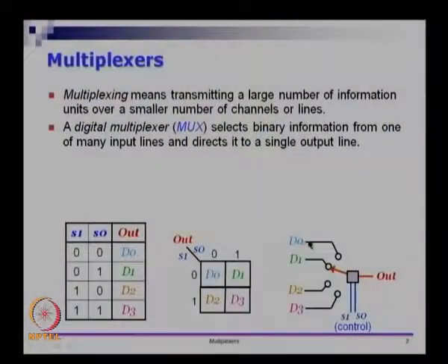So you can see a picture below. Imagine these are the 4 houses in the neighborhood and this is a multiplexer sitting there. If an appropriate control is given, one of these 4 will be connected to the output, and as long as the control is held at that, only one input is given to the output, the other inputs cannot be connected. If you want the other inputs to be connected, you have to change the control to something else.